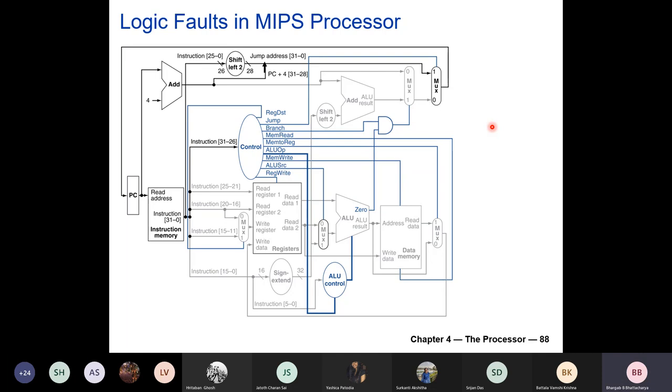Okay. And now these defects, we do not understand what kind of defects may occur. But since this is a digital system or digital circuit, we model the defects using some kinds of logical faults. So we say that we do not understand the defect, but the effect of the defect is on some logical lines. See, if we look into any logic line, if there is no defect, it may be at logic 0 or logic 1, depending on what is being generated here, right?